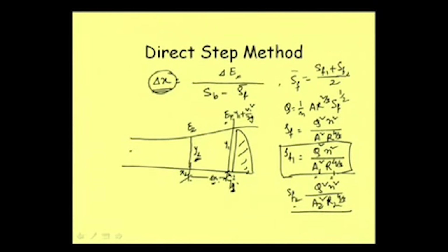Once we calculate delta x, let us put this delta x as delta x1. So after calculation, for y2 we are getting this delta x1. That means our purpose is served: we know that our y1 depth is at x1, then after delta x1 distance our y2 depth will be, that we want to know.